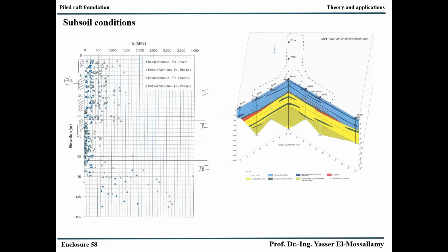At that time, I worked as a freelancer for Dar al-Handasa, and this was a project of Dar al-Handasa. They have done a lot of pressuremeter tests, and you see the E modulus of the pressuremeter with depth, and you can see something which is a surprise. The upper layers are very hard, very stiff, and then we have a weak layer, and then another hard layer.